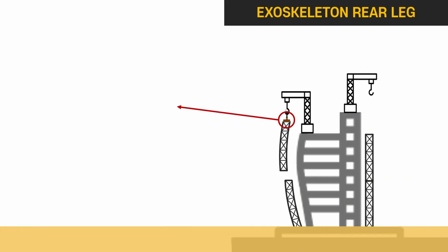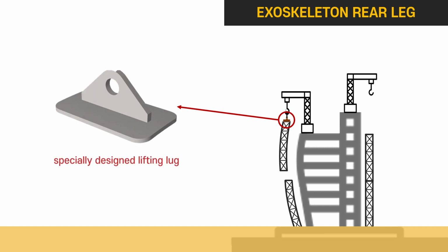When lifting, specially designed lifting lugs with a 20-ton chain hoist were used to lift the segment in the predetermined location and at the required angle. Alignment of these segments was carried out using electronic digital total stations located at three different fixed locations.